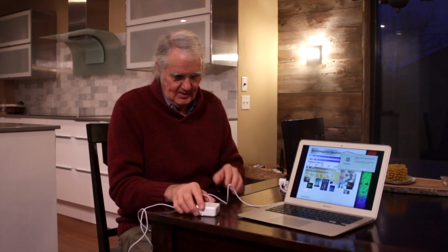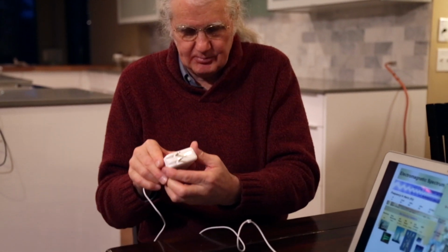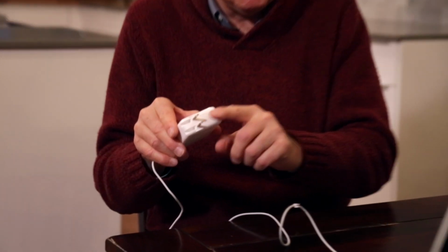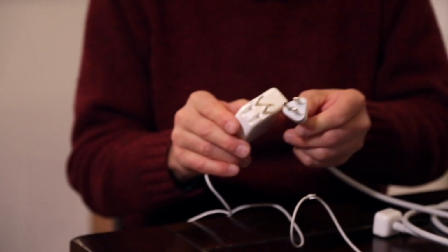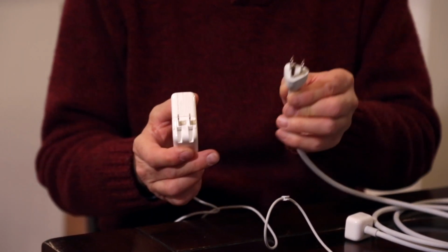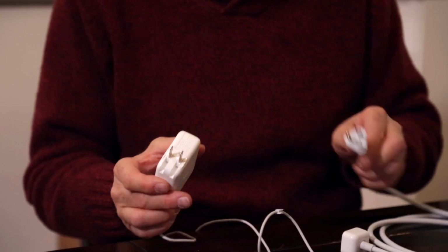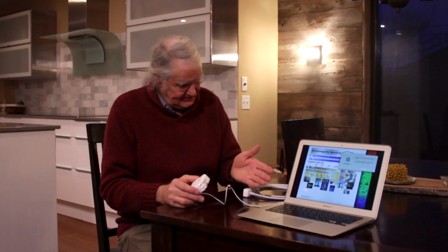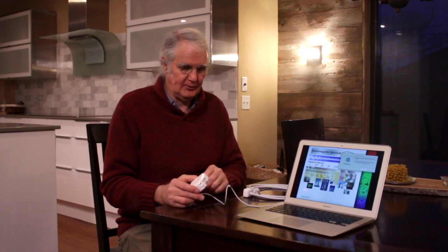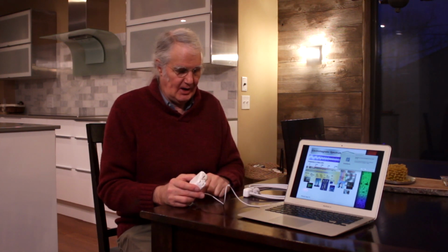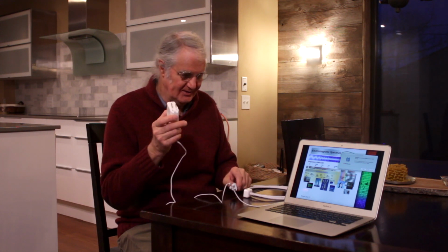But in the daytime and evening time, we can also have electric field exposure, particularly from an appliance like a computer, ungrounded appliances. This is what I mean. And what we're talking about is power cords that have a 2-prong plug on them, not a 3-prong plug. So this grounding prong here makes the difference. And that's true for laptops and desktops that we put our hands onto. It's true for refrigerators and other appliances that we are near or touch. They need to be grounded, not ungrounded.